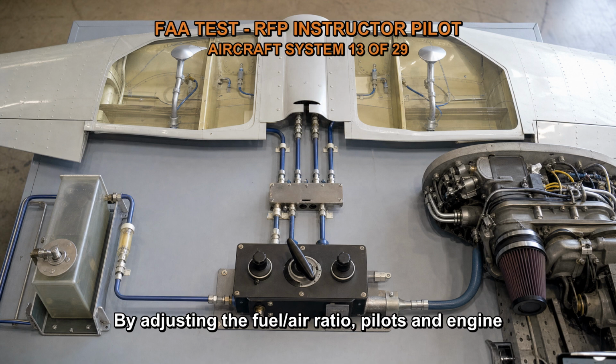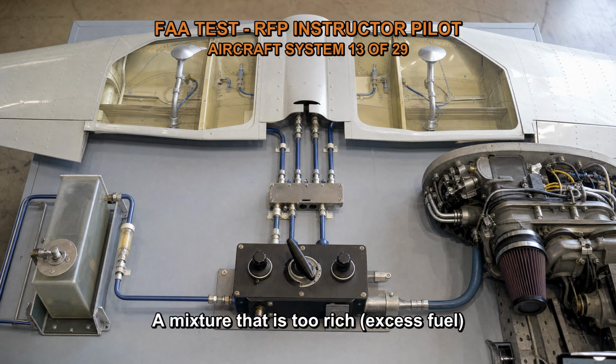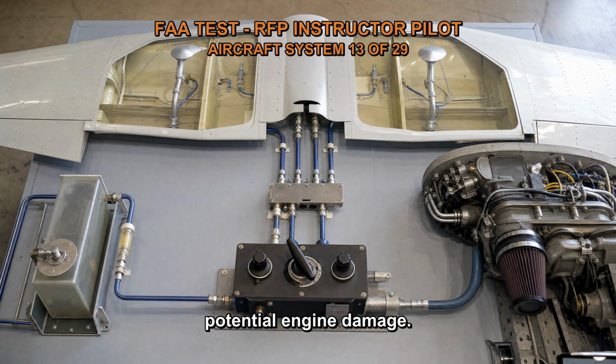By adjusting the fuel/air ratio, pilots and engine operators can optimize the engine's performance and efficiency. A mixture that is too rich, excess fuel, or too lean, insufficient fuel, can result in inefficient combustion, reduced power, increased fuel consumption, and potential engine damage.